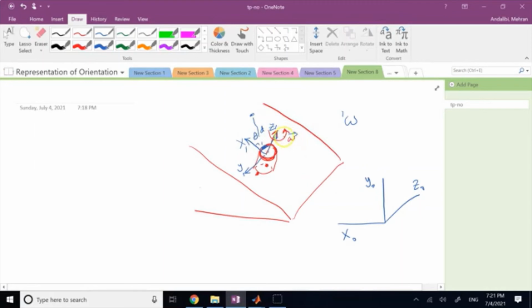But the problem is all of these, even theta and d, are measured with respect to this body attached frame. If you want to accumulate them and put them on top of each other in different positions and orientations of the robot to create a map in the inertial frame, you have to project all of those back into your inertial frame, and that's where you have to project this vector back from this frame to this frame.